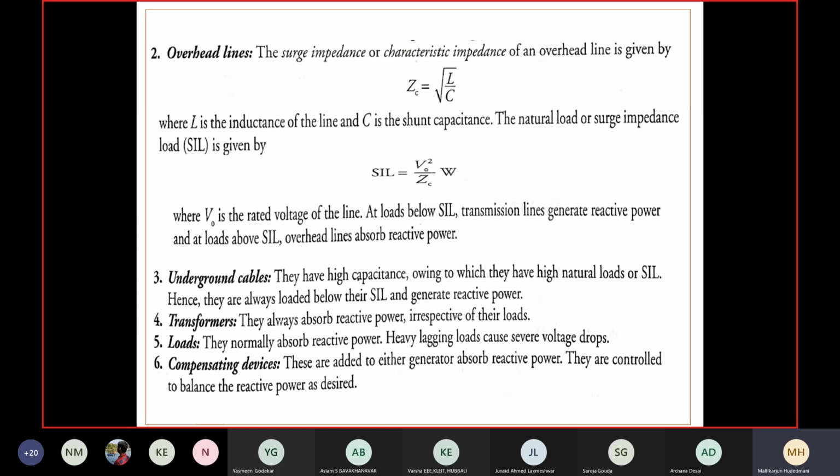It is another advantage for control of voltage. The tap changer shifts the taps according to the required terminal voltage. That incremental addition or removal of voltage by the transformer taps makes the required voltage available at the terminals. Therefore, we have the transformer with the tap changer facility perform that.